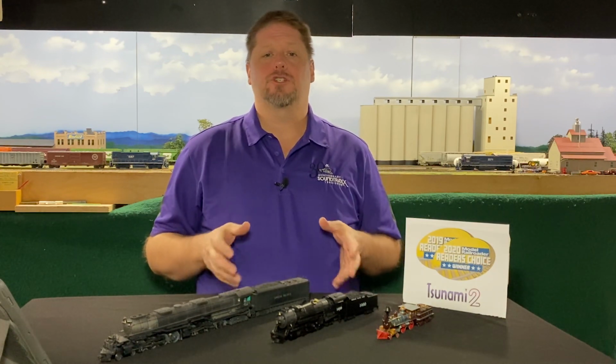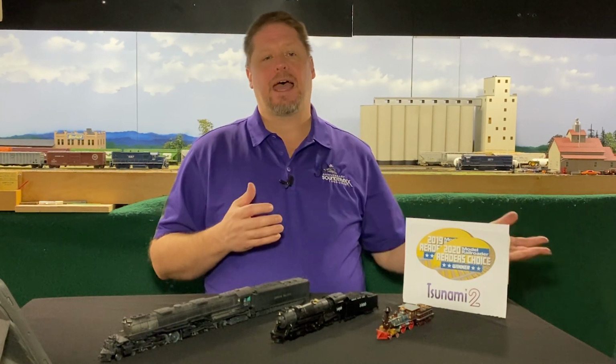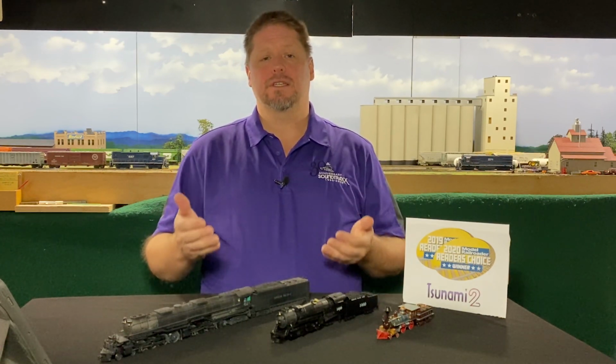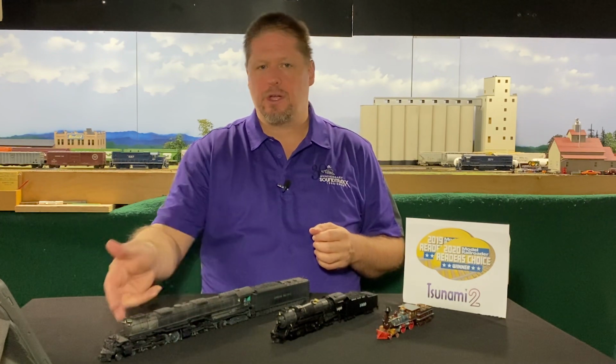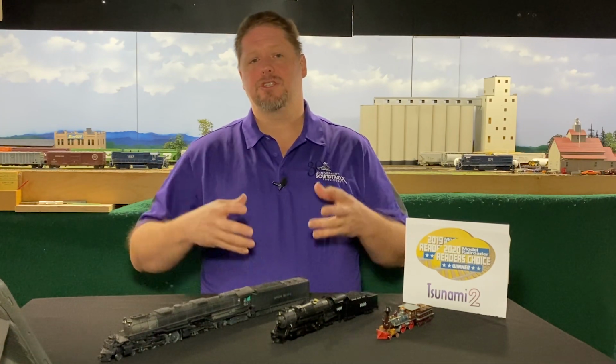Now, one of the biggest questions we get is about chuff cadence and, for example, the chuff rate. How do we set the chuff rate? Now, in years past, our decoders had a chuff cam wire, and this wire was attached to a physical cam that was located on one of the wheels of the locomotive and physically triggered internally to create a chuff. Now, the tricky part was that was difficult to install. And so what happens is you ended up having to take apart the drivers and in some cases separate the drivers.